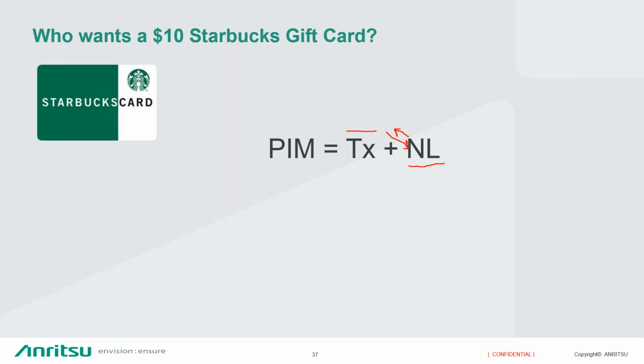What is the ratio of the optical splitter, 10/90? Yeah, we're using 70/30. That has worked with 100% of the network equipment that we've gone to today. It's very dependent upon obviously the network equipment manufacturer's optical specs and their SFP specs, but we found that 70/30 is quite a good ratio to go to market with.